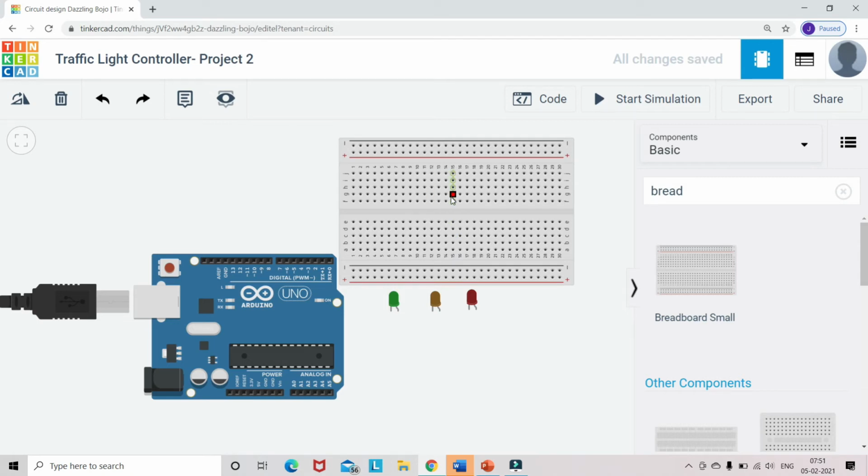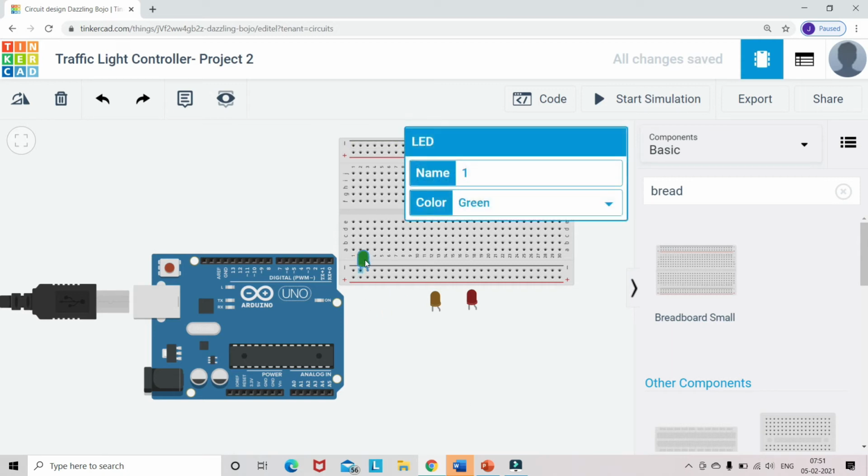Okay, if you have any doubt how it is connected, you can just keep your mouse over there, so it will be giving the hint. There will be a light, maybe green shaded straight line, that's it. Now let's keep our LED over there in the circuit area. So far you can see the cathode is in a different strip and anode is in a different metal strip, right?